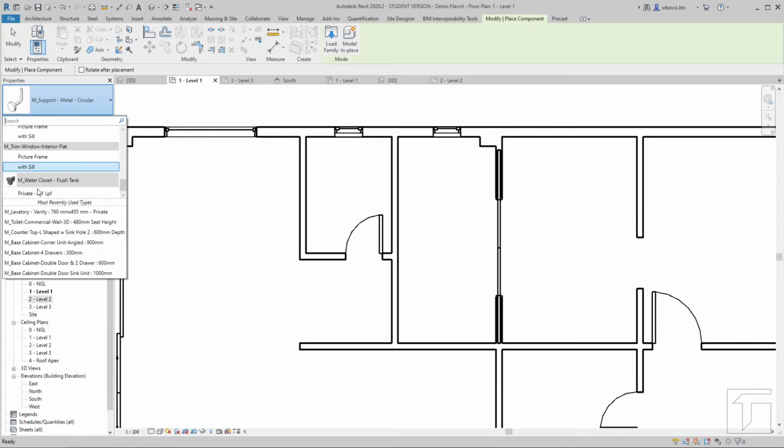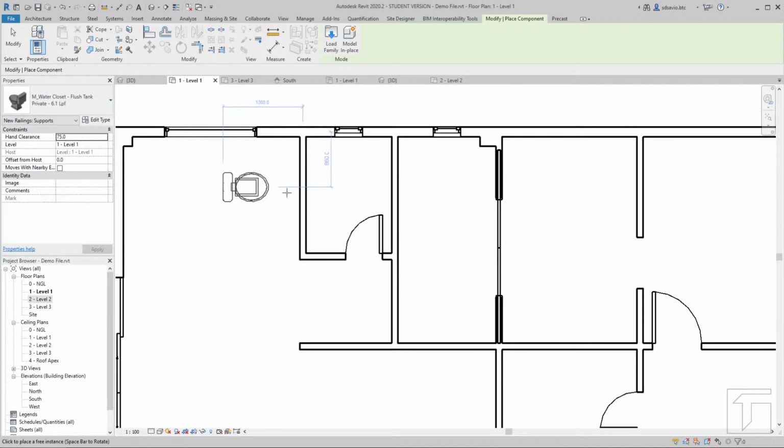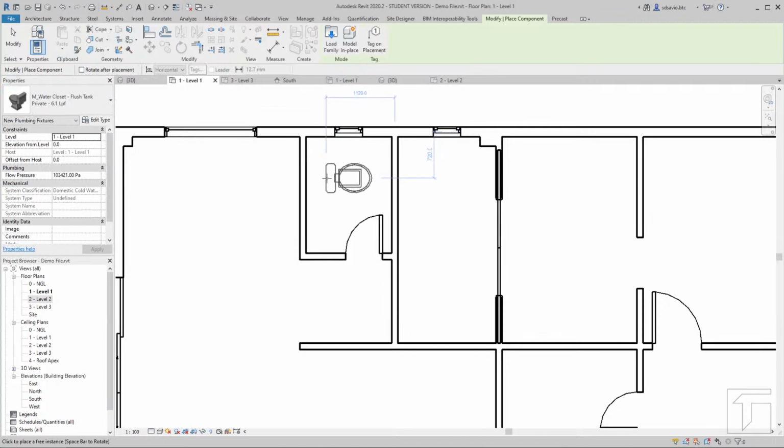Okay, so we click on this water closet there, and if you notice, the orientation is like that. To easily rotate it to be oriented correctly against the wall above, you just press the space bar, so that will rotate like that. Once it's in the correct orientation, that's the time you can now snap into place to finally place it.